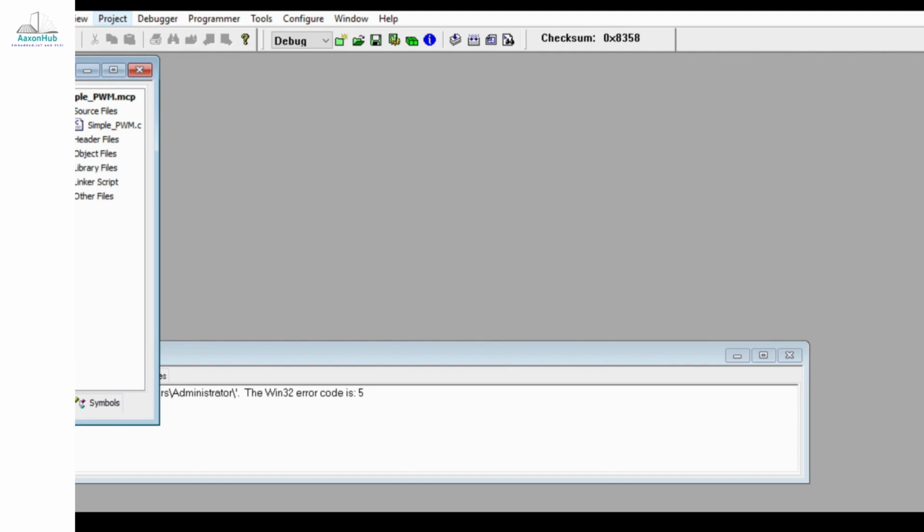So to execute this PWM DC motor interfacing, go to your MPLAB project wizard. Click on next and select the device. PIC18F4550 device is selected. Click on next. In that, select the active tool suite as the Microchip C18 tool suite. As we are writing this as C code, that's why we need to select the MPLAB C18 C compiler. After that, click on next.